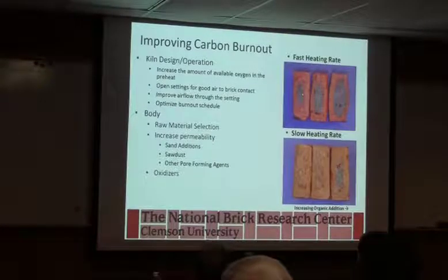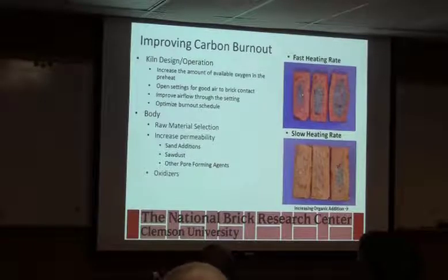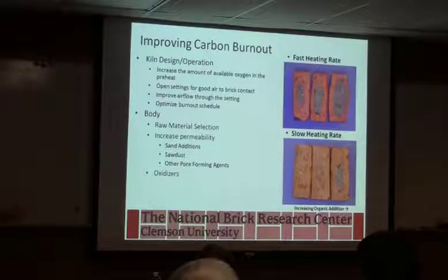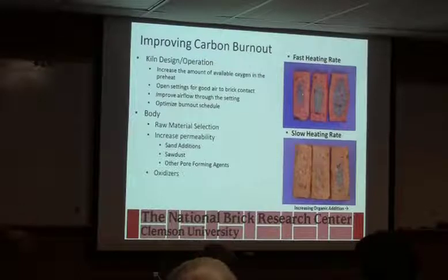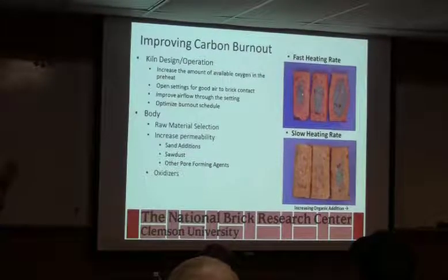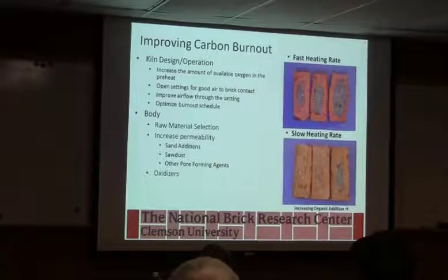Improving carbon burnout: kiln design and operation increase the amount of available oxygen, and that's where we talked about going excess air on the burners. Open setting for getting good flow around the brick so the center of your package isn't a dramatically different color or even have different hardening properties from the outside of the package.